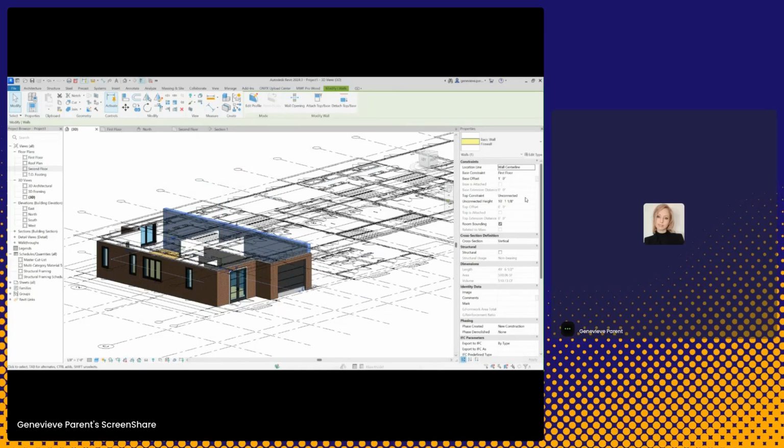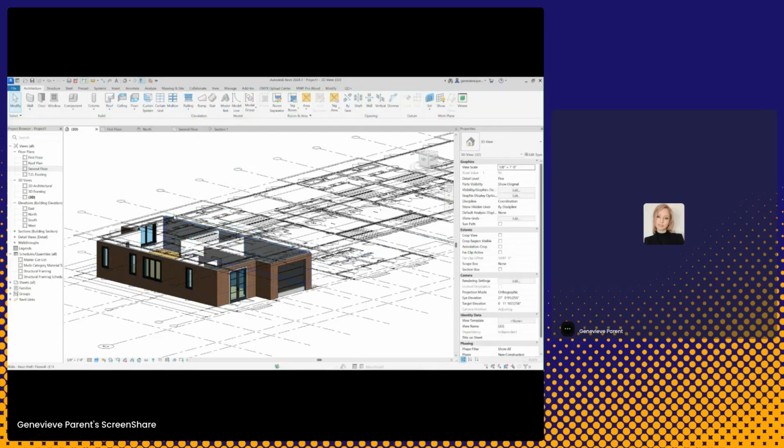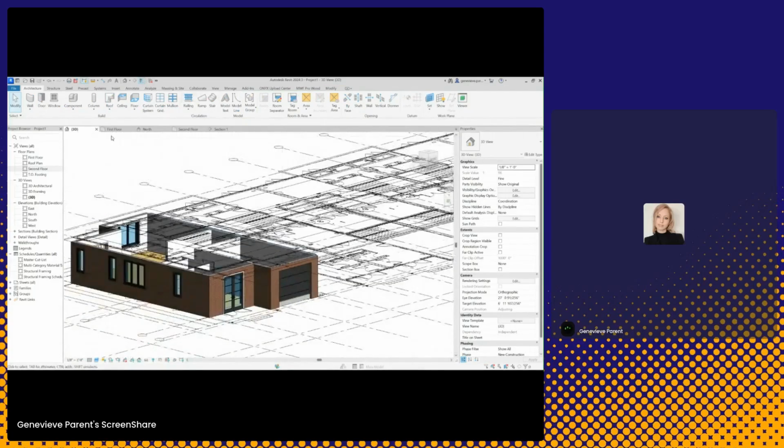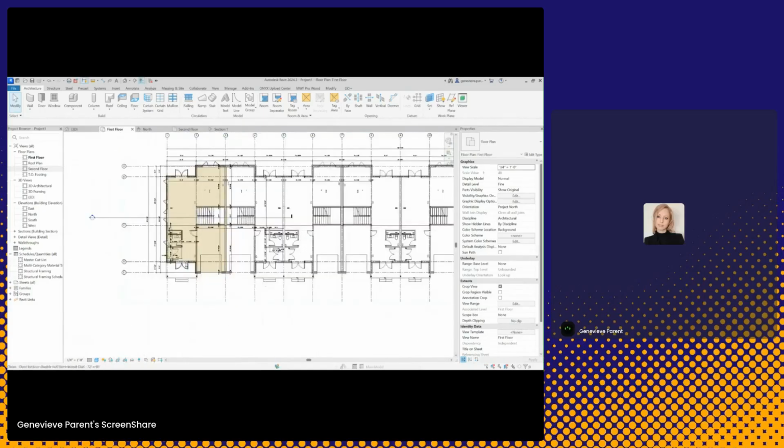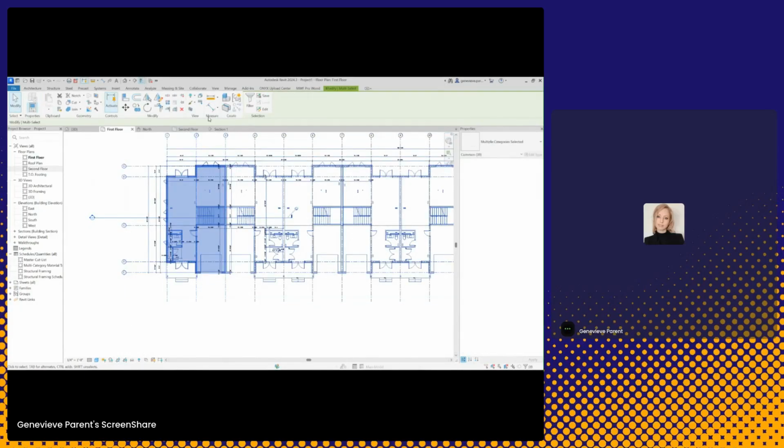This one, I am definitely going to bring it up to the top plate. Now be careful when it comes to heights. You want to make sure they land in the right spot. But essentially what we want to do, we want to trace one complete module so that when we bring this over, I can just unselect through filter. I am not going to be bringing my views or my grids or my DWG. I'm going to hit the mirror key.